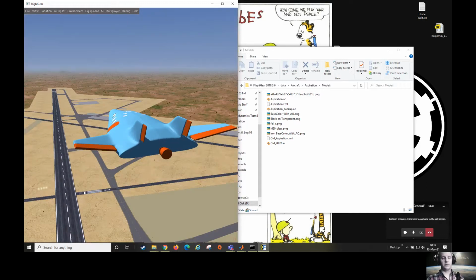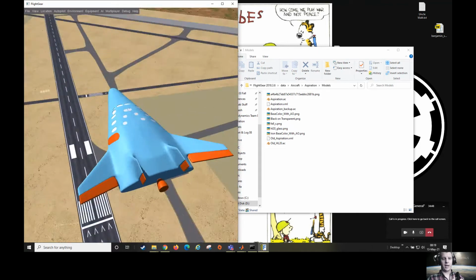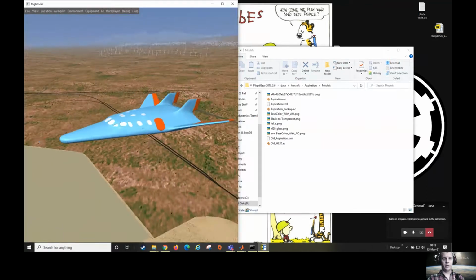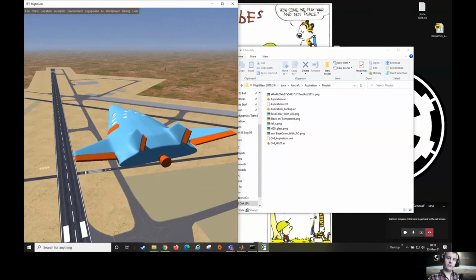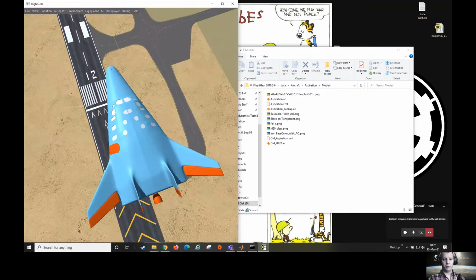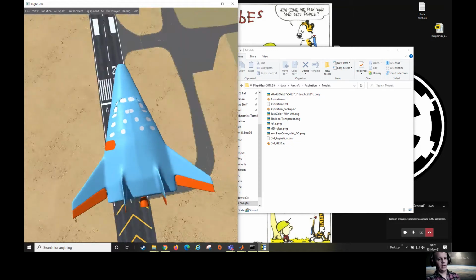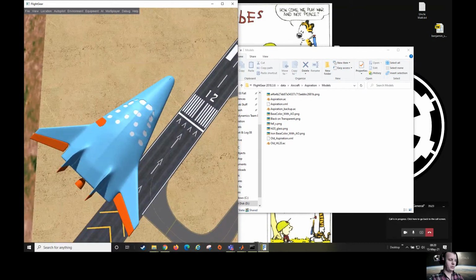Your hat will change your view in Flightgear, so it's slaved to Flightgear for viewing control, but it's also slaved in Simulink as the RCS thruster control. So you can pitch down, pitch up by pulling back. If you go to 45 or minus 45, that's going to be your yaw thruster control. And if you go right and left, that's going to be your roll control for thrusters.